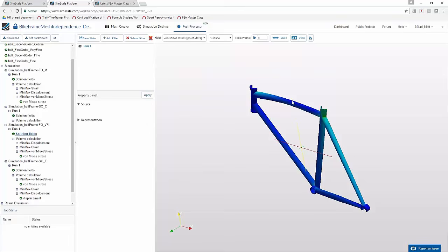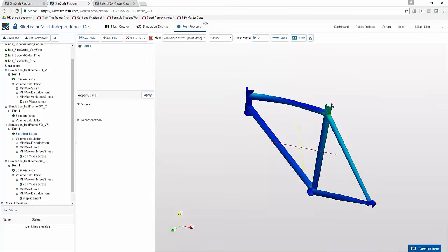And so what we can do right now is go a step back, use the coarser mesh, and add local refinements everywhere where we see a high stress. And this in the end will help us to receive the smallest possible mesh independent solution.